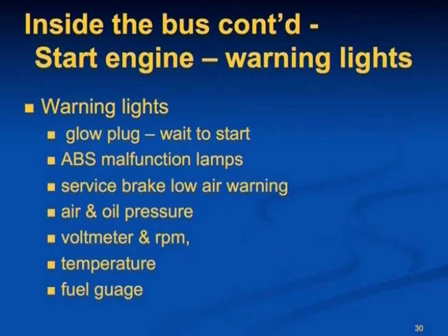Temperature gauge warning lights indicate what the temperature of the coolant is in the engine. Your bus may have a gauge or a warning light. The indicator should read cool or warm. If it indicates hot, the engine should be stopped immediately and the problem reported.